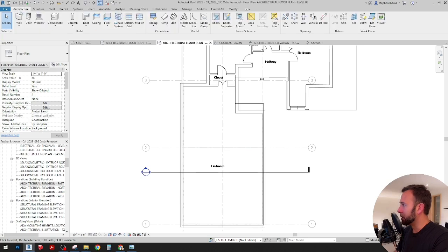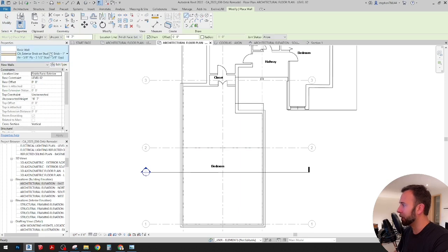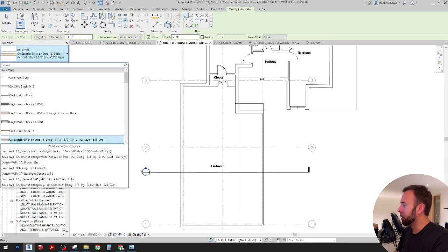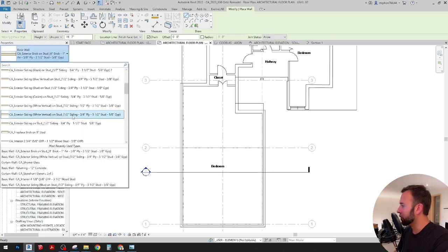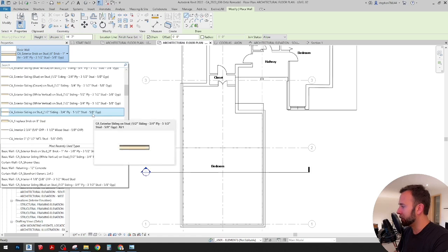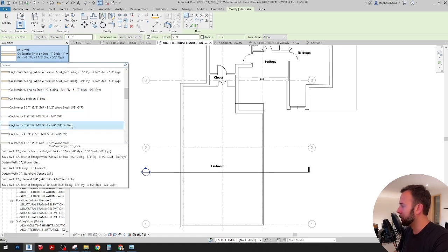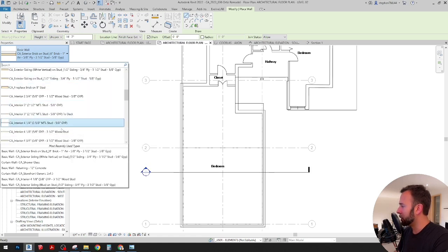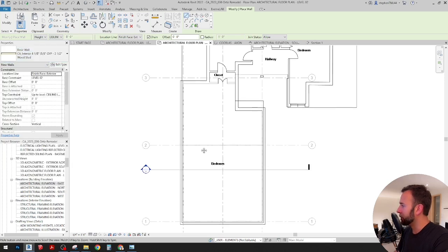So if I just take a standard wall, and I can't imagine we would drywall the inside of these walls, so I'm going to do something more like a standard 2x4 interior stud wall with 5/8 inch gyp only on the exterior face. So I've got a stud wall type for that right here, 5/8 inch gyp. Click on it.